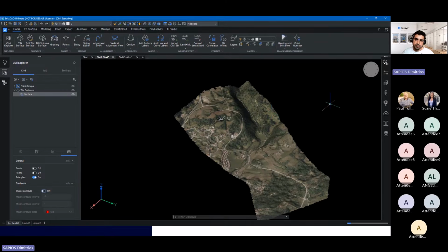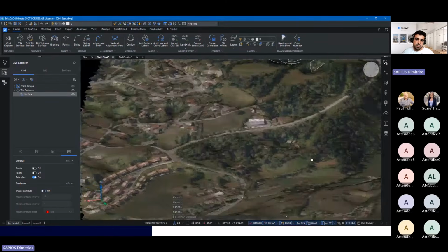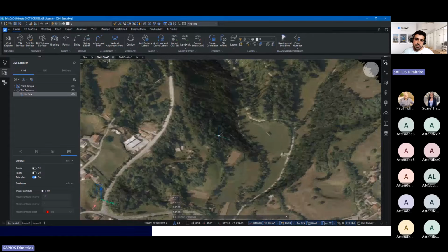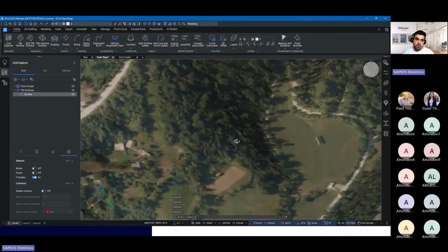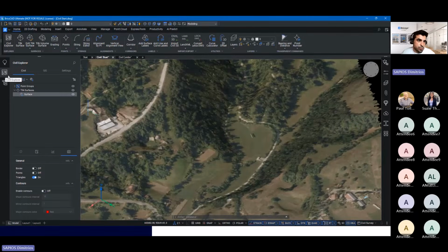There you go. And let's zoom in on a specific region right here. The way that BricsCAD works with gradings is this: with this functionality, we use a 2D or a 3D polyline in order to create an input entity for the grading. Let me give you an example.